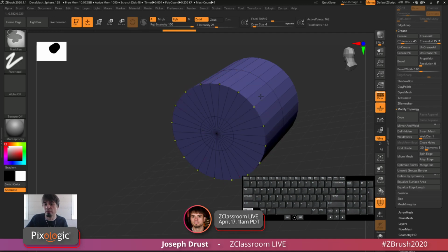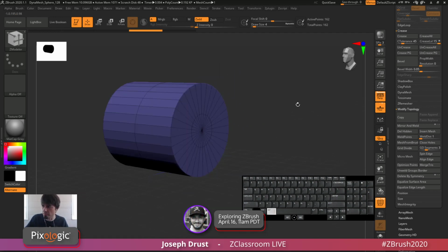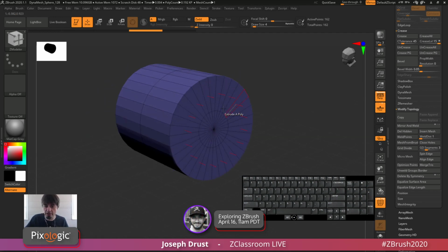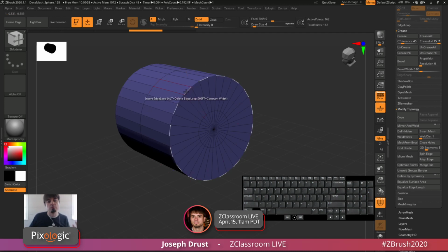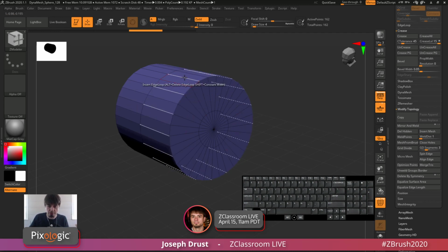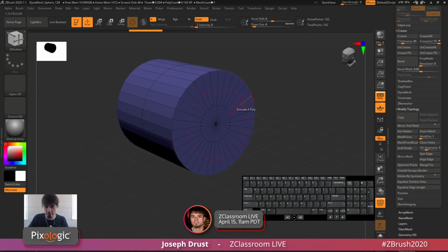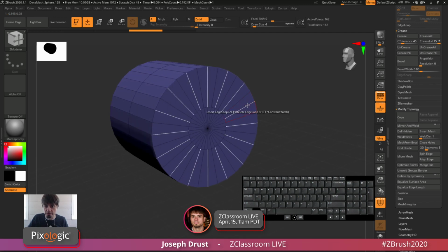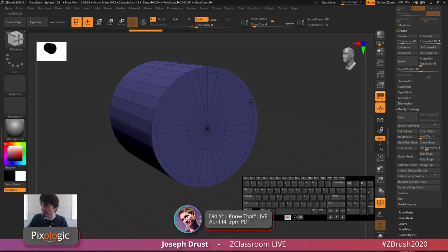So I could do by 4, whatever those powers that would go down evenly, you can start modifying your shape. Now what I like doing for the tire here is first I'll establish the inner shape, and then I'll establish the edge rim, and then I'll usually establish the tread in the middle. And all this is using pretty much radial symmetry as I do this. A lot of insert edge looping, so I'll come in and just start inserting stuff.